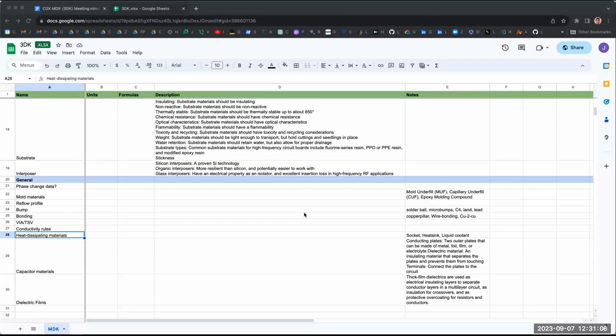I would add to the general list all the heat materials, like TIM 1, TIM 2, those things, just so that they get captured somehow. I think the list captures it, but we'll make it more explicit. You have cold plates and heat sinks, so metal. We should be a little more clear on the terminology. The thermal interface materials are needed there to conduct the heat.